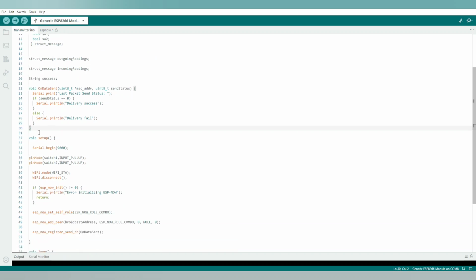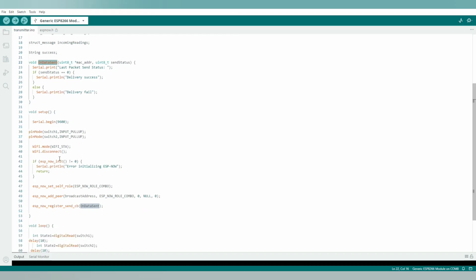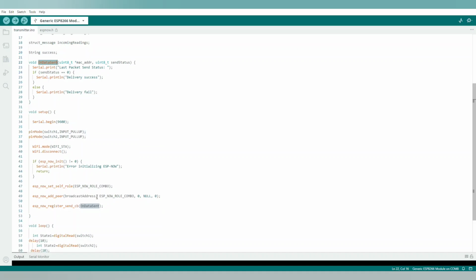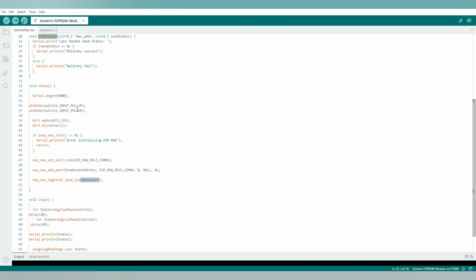So these stay as the data, transmitting the data to the receiver. Here we are keeping the switch active high. Just switch on and keep it down to low, and every time the signal is transmitted. You can also reverse it, keep this switch active low and make it high, so the signal will be transmitted as per your choice.